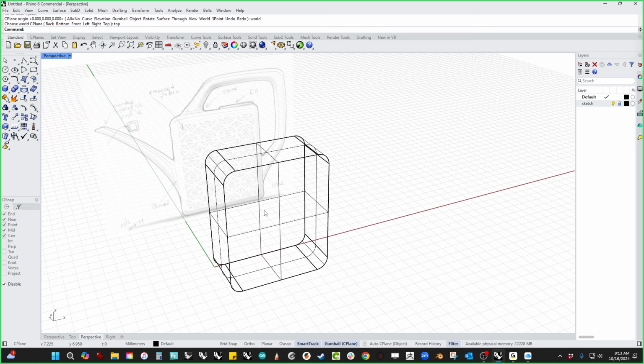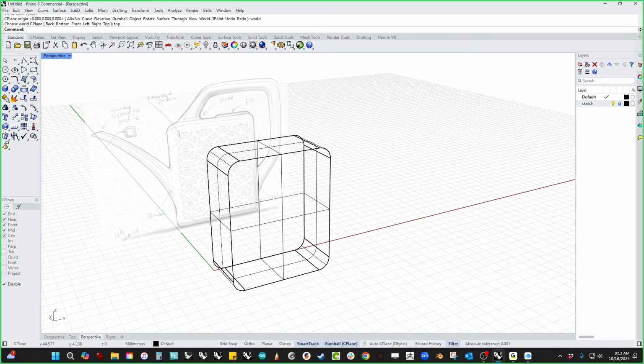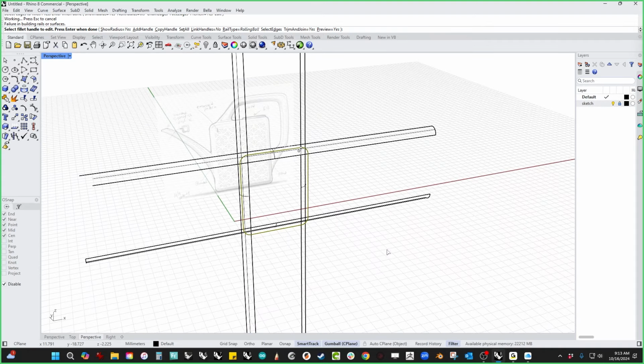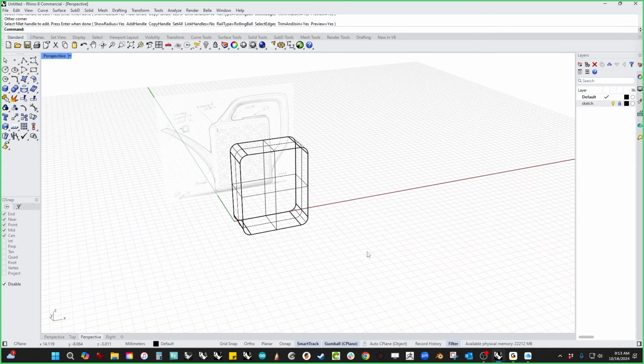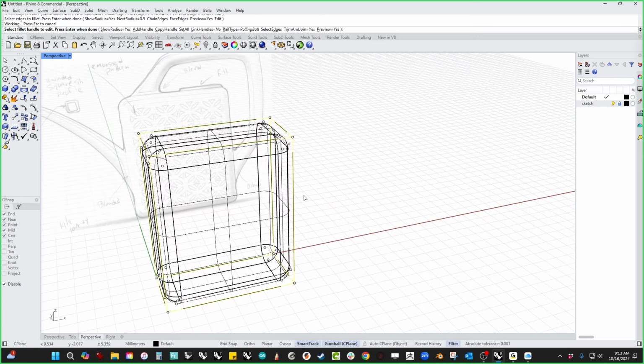Now, because we used 0.95, right? We can only use 0.949 or smaller on these edges. If I do 0.95, and I'm going to check myself here and see if I'm being a liar, but if I run 0.95 on this again, or 0.9 on this again, it is likely going to fail. Now, if I did this and did 0.95 on everything, it's going to work.